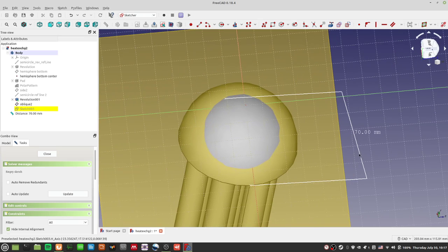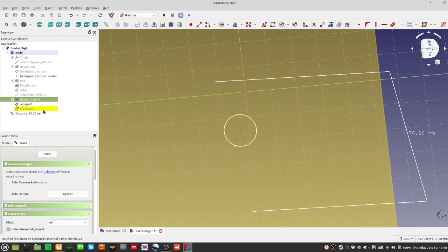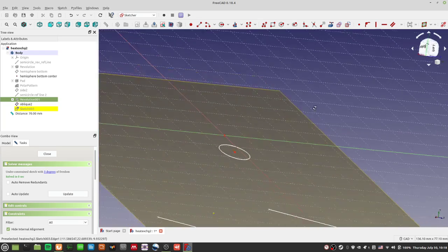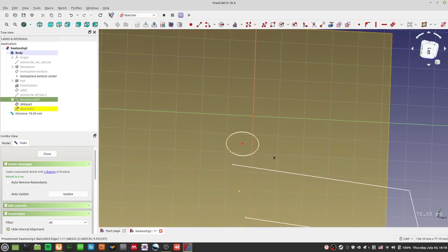Now I'm roughly satisfied, and I want to aim for my little cylinder right over here. Basically you can't see the cylinder at all. If you cannot see it at all, you just press the revolution, press spacebar. You'll be able to see that. So we see two datum points there.